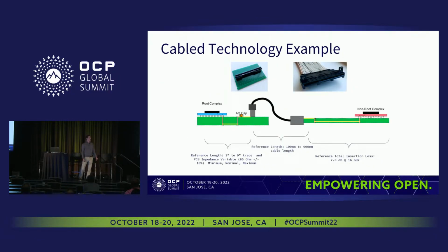And then we look at the cable topology, which might be somewhat new to folks here, as it's a little bit different. It's the same root complex with the via and host trace, but then we put a vertical SFF-TA-1002 connector, and then an SFF-TA-1020 cable assembly. And then this has a direct-to-lead frame cabled receptacle on the other side that would alternate with an OCP NIC.